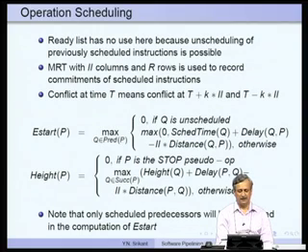So, that is why, if we are going to begin another iteration II cycles later, conflict at t implies conflict in the next iteration also, which is started II cycles later, and there would have been one iteration running II cycles earlier also. So, conflict at t implies conflict in the previous iteration and the successive iteration, which were started II cycles before and II cycles later. So, that is what this really says.